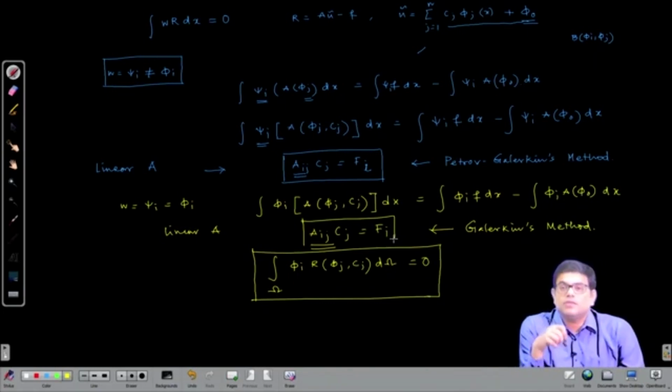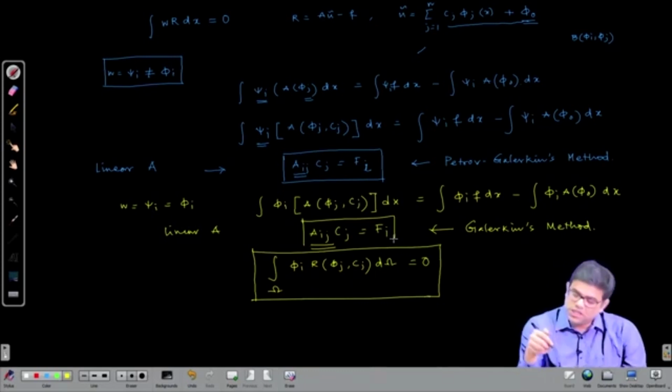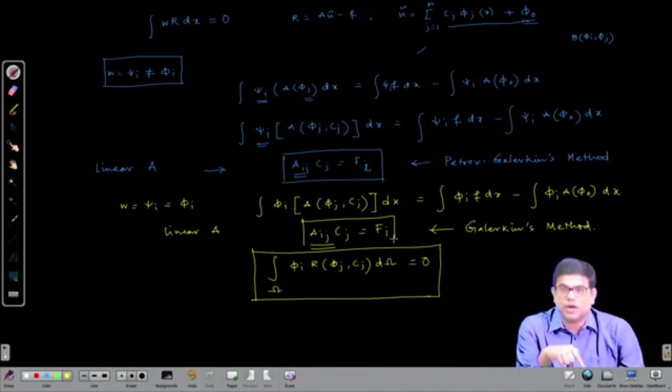In case of the Galerkin method, this process can also be performed if the function or the differential operator allows us to do it. I will show with an example that the differentiability requirement can be reduced in Galerkin's formulation and transferred to the weight function, and then obviously the natural boundary condition will automatically arise.